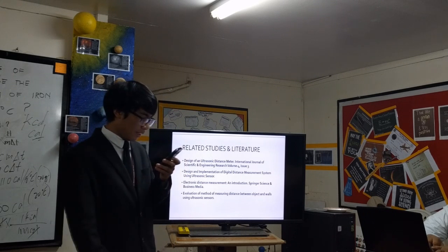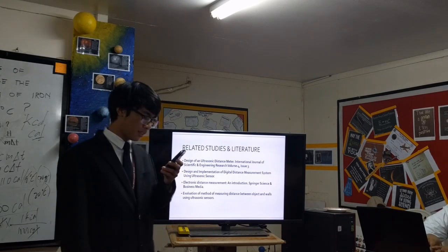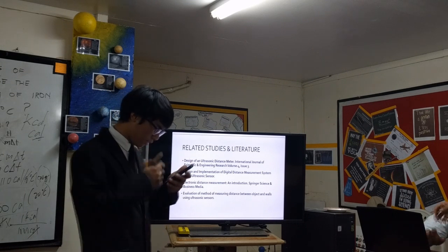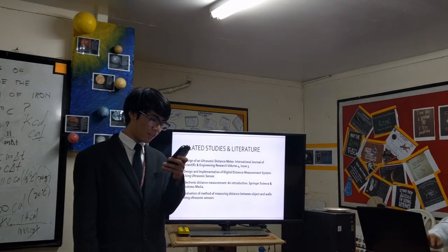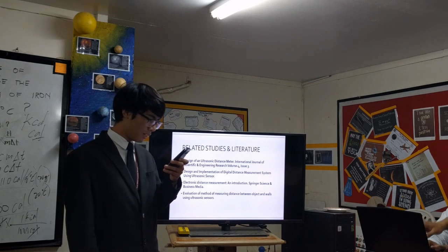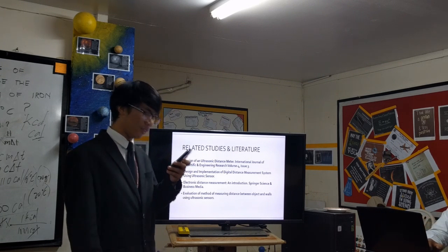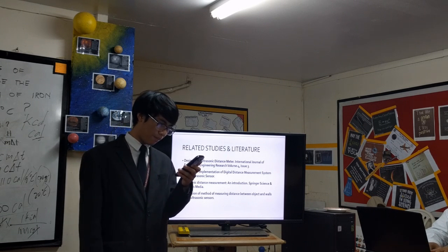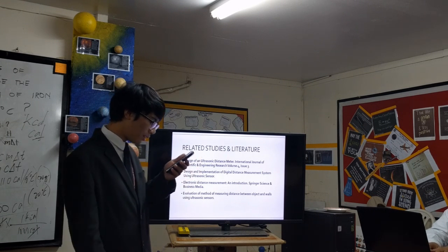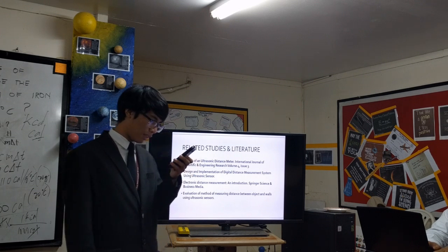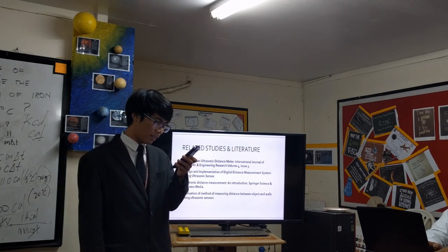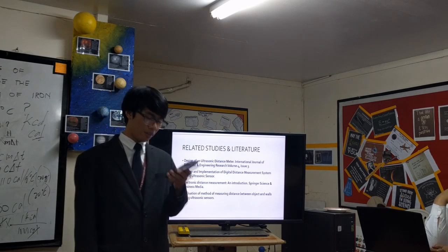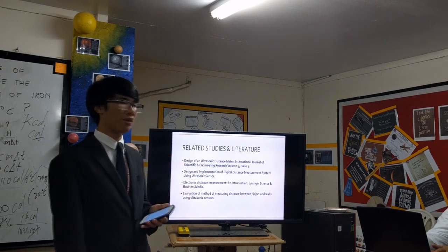Second, the relatively short ultrasonic wavelengths allow more highly accurate distance measurement. Third, ultrasonic is not affected by the transparency or color of a surface. Therefore, measuring the distance from such objects does not affect the measurements. And finally, ultrasonic is not affected by light and airborne dust, allowing it to perform distance measurements in outdoor environments.